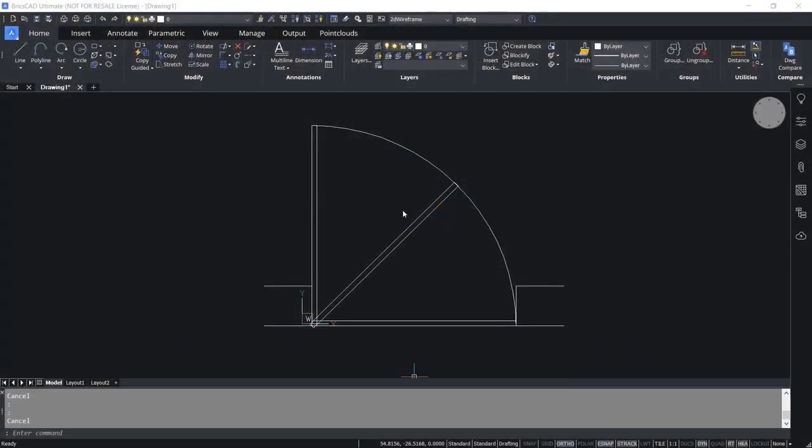Let's start with the drawing of a door. I've shown the different positions of the door shutter in a single drawing. This is the open state, this inclined position indicates the half open state, and this is the closed state. Then I have also used two arcs to indicate the door swing direction, and these lines indicate the wall thickness.